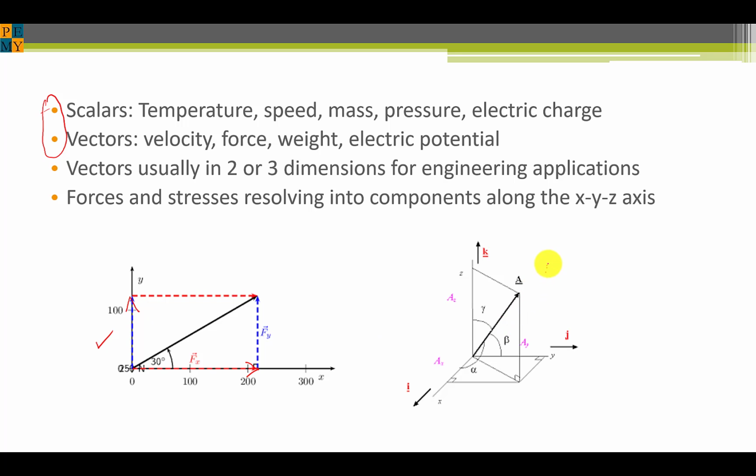In 3 dimensions, we do the same thing with any 2 dimensions and do it twice. So for example, we first get the projection of the vector on the z-axis and the projection onto the xy plane. Finally, we can use trigonometry to resolve the projection in the xy plane into the x-coordinate and the y-coordinate. Therefore, we end up with the 3 components of this 3-dimensional force.